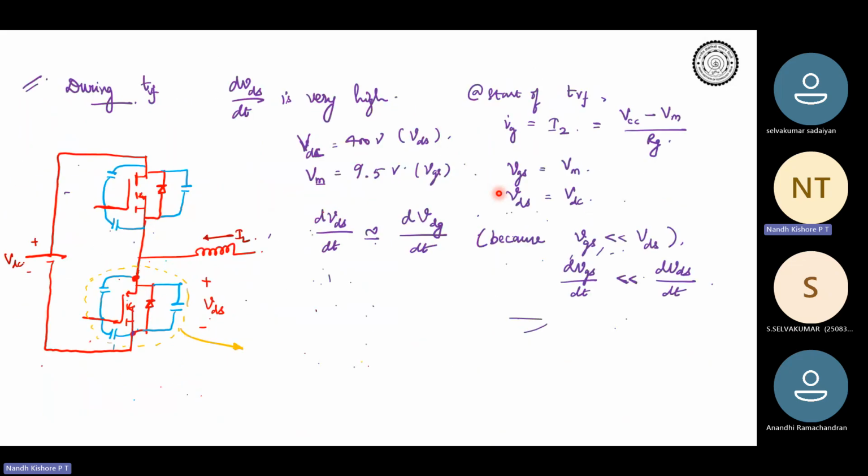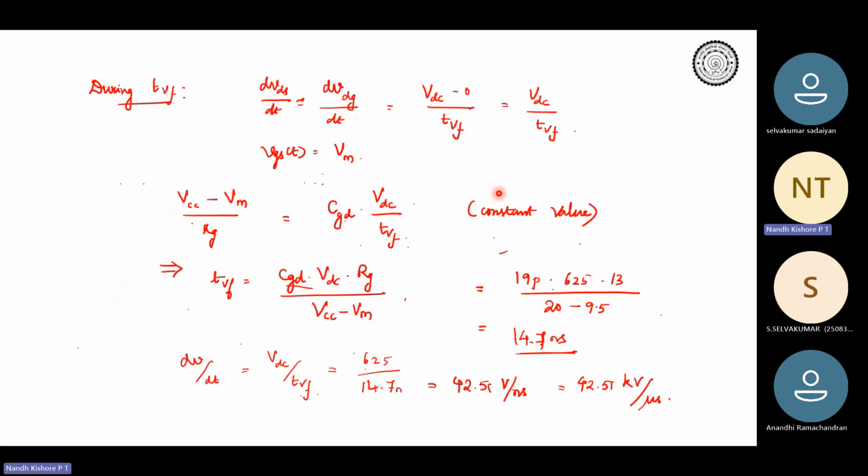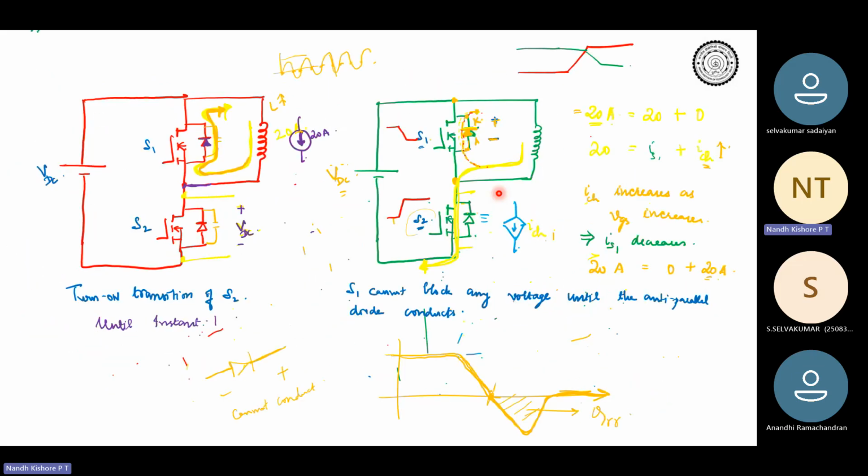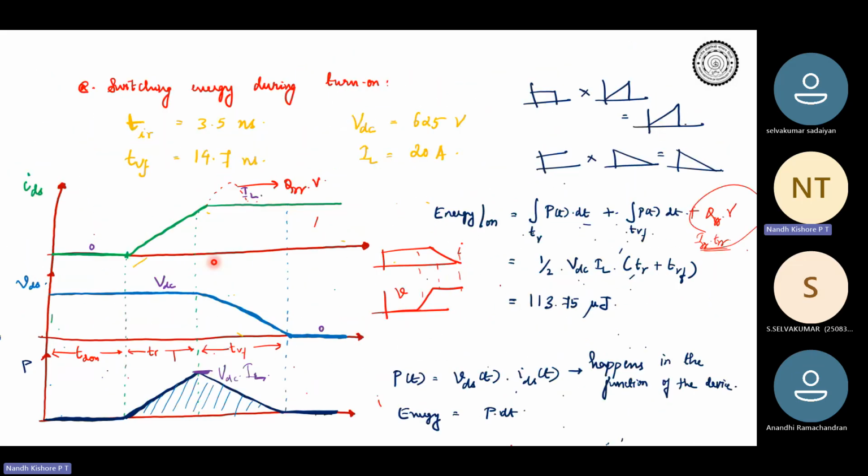Towards the end, we saw that once we know the switching time, we can compute the energy. You have your current waveform and voltage waveform, you compute the instantaneous power loss, and then find the area under the curve. The area under a power curve gives you the energy. This energy loss happens every time the device turns on and turns off, so when you multiply that with the switching frequency, you get the average power.